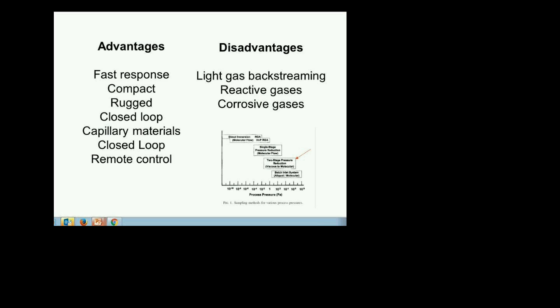Well, I wash them. Basically, the baking in hydrogen is to remove the oxide films. We're baking refractory metals like molybdenum. They oxidize in air. The oxygen is removed by turning into water, right?